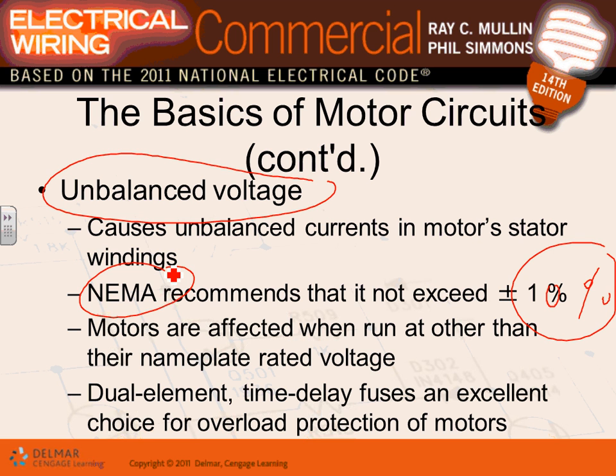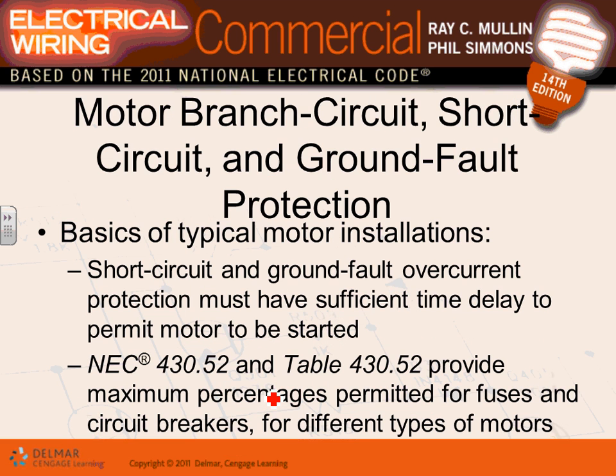We can use dual element time delay fuses as a good backup overload protection for motors. Dual element time delay fuses, they use them either alone or in addition to a heater or an electronic overload to provide overload protection for motors. And we'll talk about this one. Ground fault short circuit, guys. You have to provide the short circuit ground fault protection. That's all coming from the table.